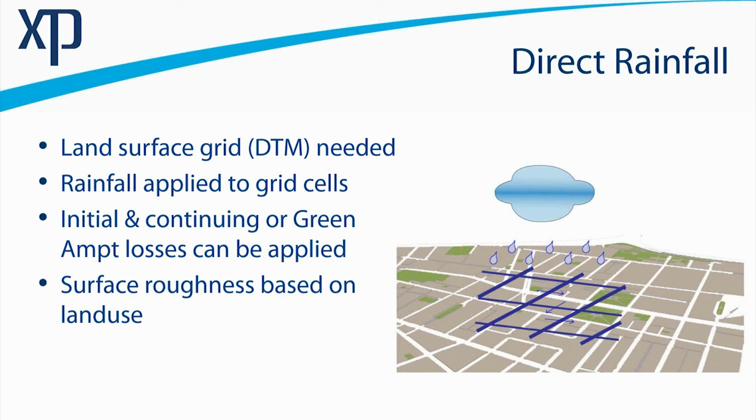There are some limits to it in that you do need to have a relatively fine terrain data set. That's our biggest limitation in the short term. Secondarily, you need to understand your land use, and then also the impact of surface roughness elements. Those surface roughness elements could be in the form of a building, because typically when we have our aerial survey, we remove or filter out buildings from the surface, and so water would inherently try and flow through where a building is, and of course hopefully your buildings are generally impervious at their lower components.